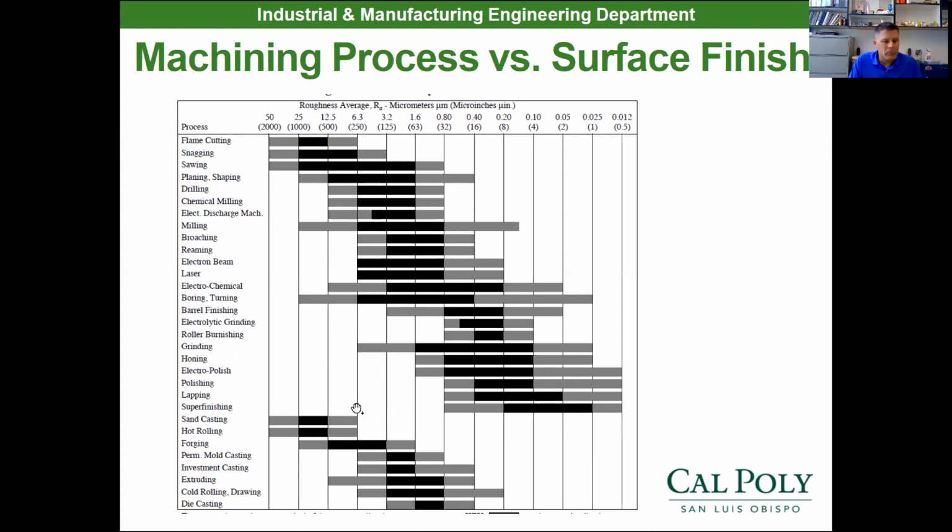If you look at lapping, we can get down to basically 0.025 micrometers, or about 1 microinch. It's pretty impressive for surface finish. In machining, for most of the stuff that you machined in class, I would say those Geneva drive wheels are probably about a 60, probably like a 40 surface finish, between 63 and 32 for our milling.